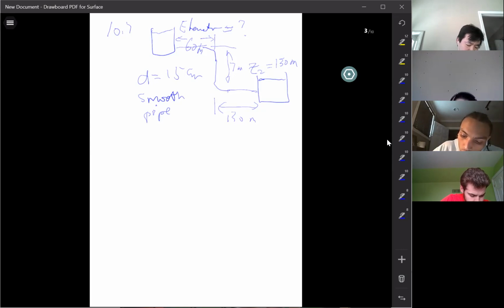You have two bends there. It gives you the R and D. The radius versus the diameter of the pipe for the two bends is 2. I guess you need to look at that figure I sent you, the minor loss table, not the figure, the table. Turn on your phone and look in the group chat. You have two 90-degree smooth bends here. Look at the definition of R over D.